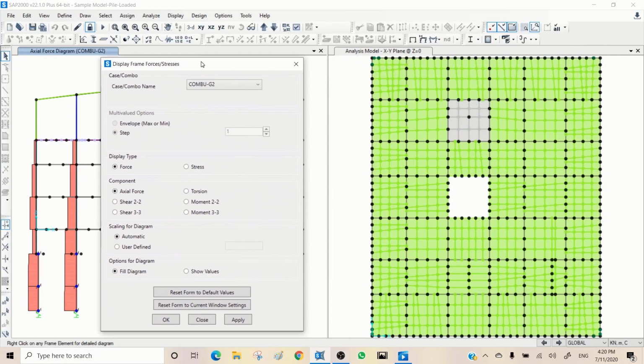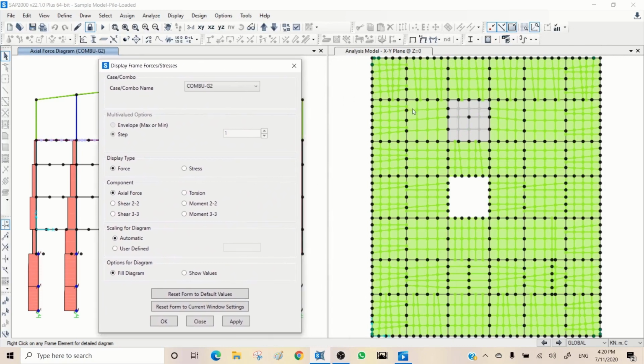Now let's have a look at ground floor slab. If you remember, we didn't have those joints on the frame, so the shell was not auto meshed properly, and the load from shell to beam wouldn't be transferred correctly. Now we've done all of them. Let's have a look at this shell in more detail.